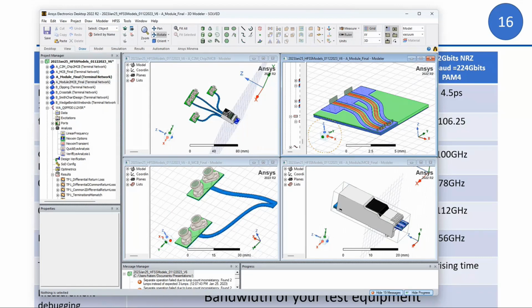I did the de-embedding. Some people, when they do de-embedding, by the way, try to de-embed their structure to the first disturbance. You are aware now that this is not correct. The field starts changing way before that, so you have to stop before that. The same argument, by the way, applies to the ports. No matter how much we try, there is a discontinuity at the ports, so the de-embedding is not correct. There's a small error that we have to live with. The right way to de-embed things is to do calibration. We will talk about that maybe in another webinar.